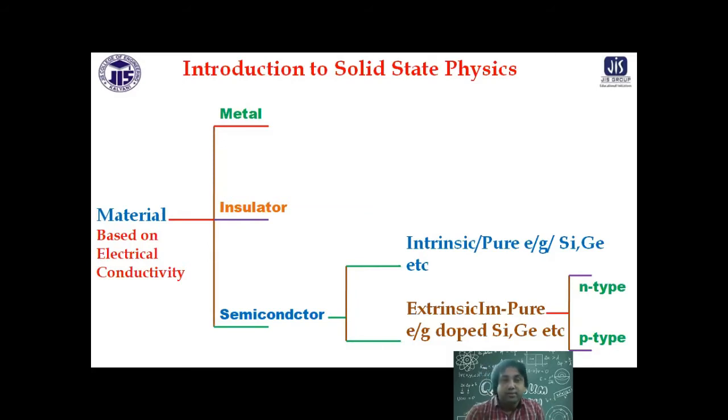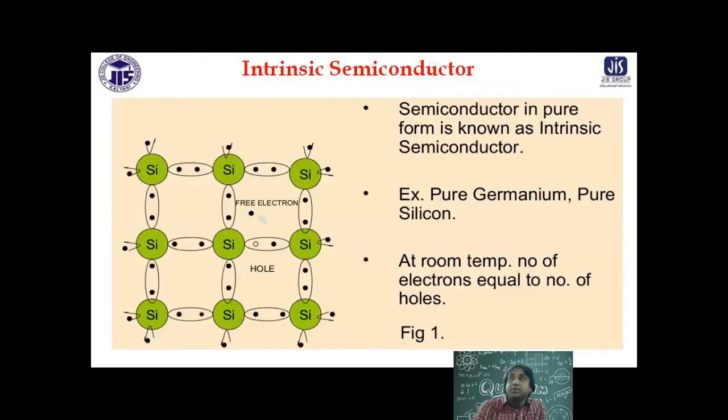Basically, that's why it is a very good example of a semiconductor. If an electron moves from the valence to the conduction band, then holes are created. In an intrinsic semiconductor, the electron and hole concentrations are the same. And the other part of the story is the doped semiconductor. That means you add more electrons into the system. That is called N-type doping. If you add more absence of electrons, or holes, into the system, that is the P-type doping. So this is something we discussed.